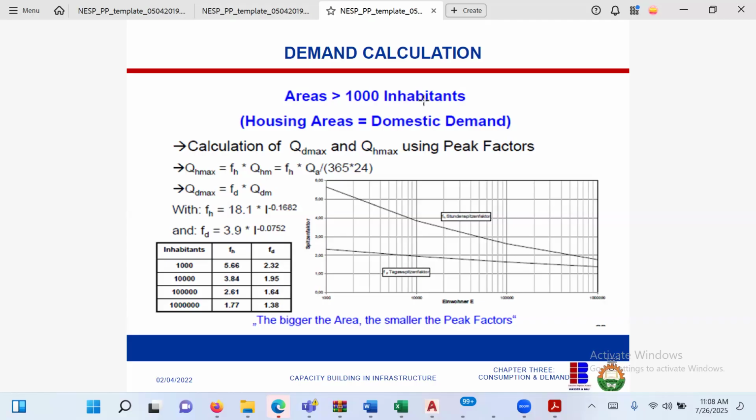Once you mention safety factor, it's an accumulation of many things. It's an accumulation of oversizing, undersizing, future development, change in lifestyle, anticipated water losses, anticipated population explosion, anticipated design error. So factor of safety can comprise five parameters. This is where engineers hide their uncertainty, because engineering is a science of approximation.